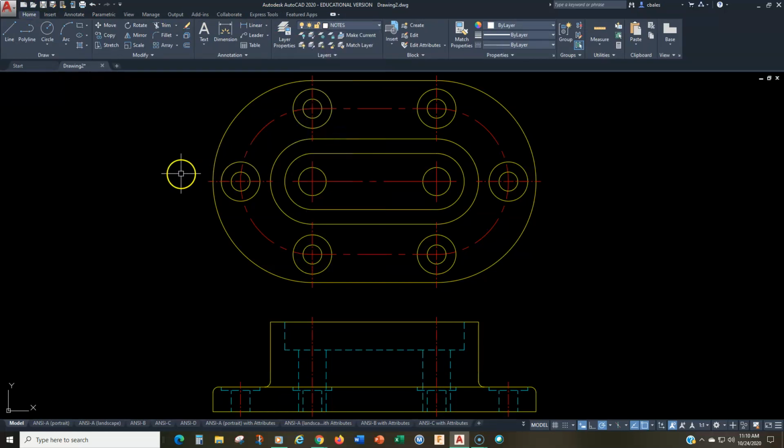And I'll draw it on the notes layer. What we're going to be doing is we're actually going to be drawing a line or cutting right through there. All right. Right where that white line is. That's where we're going to be cutting our object in half. We're going to be discarding the front half here and looking at it, in the front view, as if this is the only half. Okay.